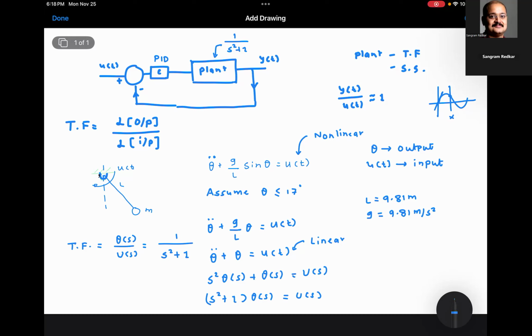So if you come to Robotics 2, here is what's going to happen. The quadcopter dynamics or the fixed wing dynamics is nonlinear. So we are going to linearize that airframe dynamics at different regions. We are not going to do that by hand. We are going to derive the equation of motion for the aircraft, and we are going to use MATLAB to linearize at different operating regions. For example, when the aircraft is turning, that's an operating region. When the aircraft is in level flight, when the aircraft is taking off, we would find the linearizations in those regions.